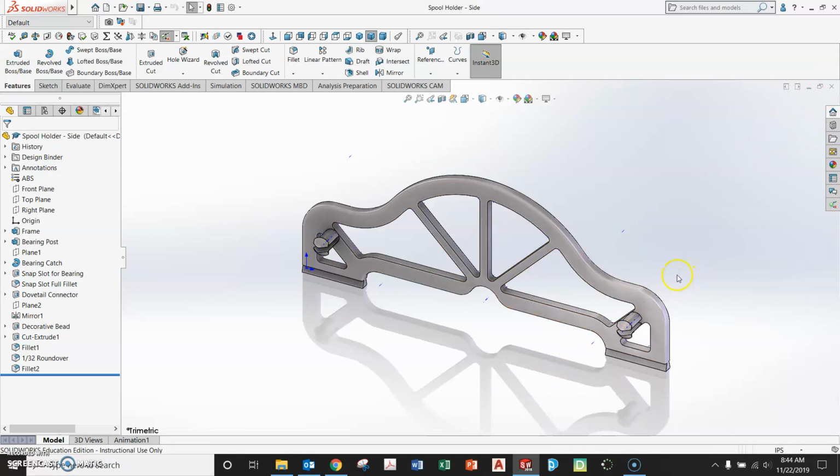So now that file type can be brought right into the software for any of the 3D printers. Like I said, you just want to pay attention to the units based upon which 3D printer you're going to use. So for the big Dimension 1200 ES, we want to do it in inches if you're using Catalyst, or if you're going to use the newer software that they have out, called GrabCAD Print, then that one is based in millimeters, but it could actually be switched either way. So in that case, I would want to export it to millimeters if I was going to use that one. If I'm going to use the Dremel, that also is based on millimeters. So the Dremel 3D slicer would be a millimeter based setup.